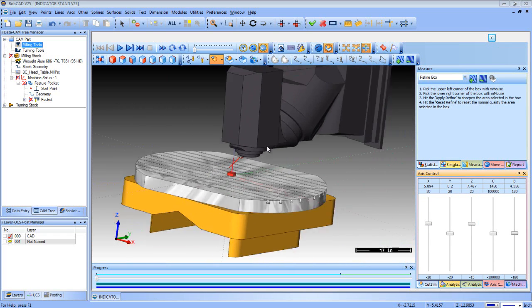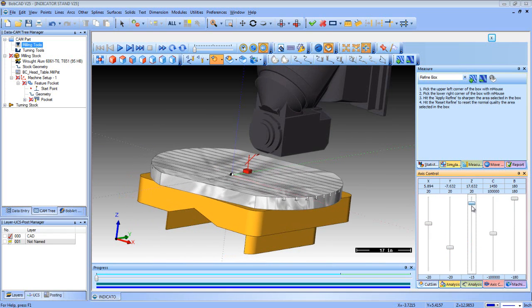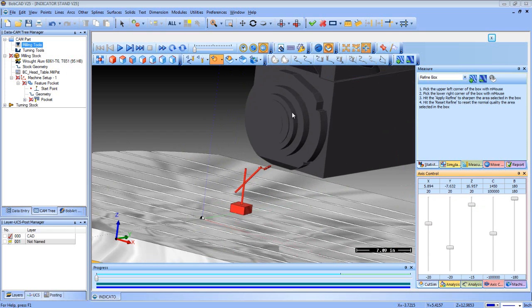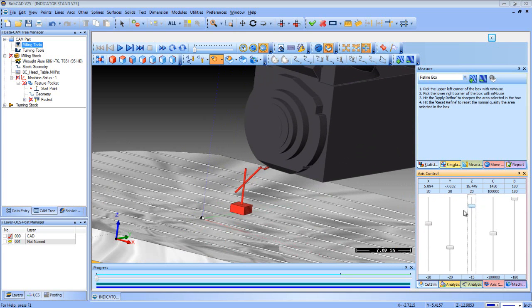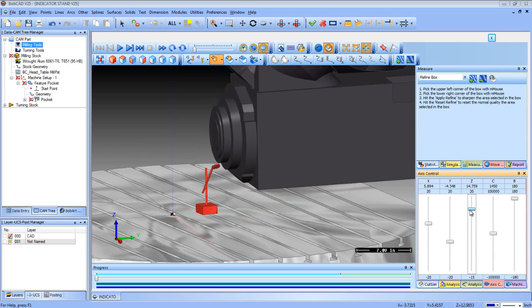Then what we're going to do is lift the head up and rotate that axis 90 degrees, so my tool face is 90 degrees. We're going to bring it back down, and we're going to pick one of the rings of it. Like for this one, let's use this ring here. So you'll bring it back down. I've got to get it lined up here, see where I'm at. A little bit of glare on there makes it tough to see. You want to zero on the lowest point of this, and you want to get that lowest point to where you hit that same machine zero. So you don't want to move the indicator during this process. Once you have that, you're going to record that number as Z2.